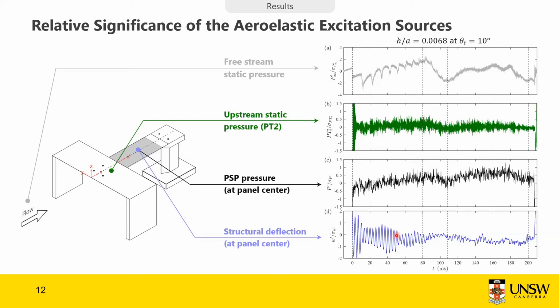That's expected because of the flow arrival impact load. But as we move on through the run, that response is getting shifted towards a fluid dominated one, which means that forcing mechanisms are present here, either due to the free stream fluctuations or the fluid structure interaction that is being developed. We can see that via the fluctuations in the envelope of the structural deflection signal.